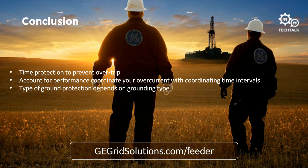You can do that with your pickup settings. You're going to do the same thing for a ground overcurrent or even a neutral overcurrent. You're going to calculate your available fault current, and make a decision around pickup on how far into the power system you want it to reach. Typically on both of those, you want it to reach as far as possible, because that way it can provide backup to other devices, but then you have to coordinate them.